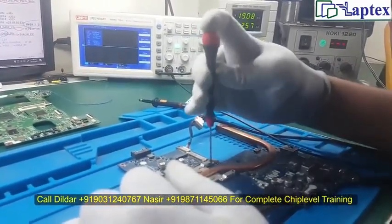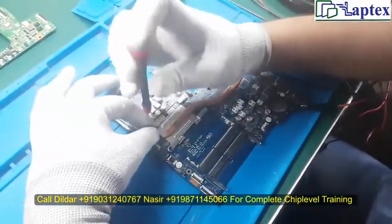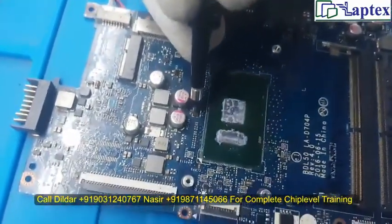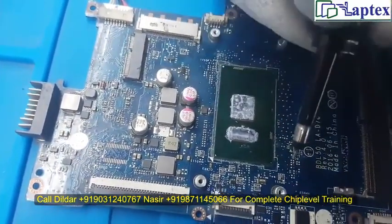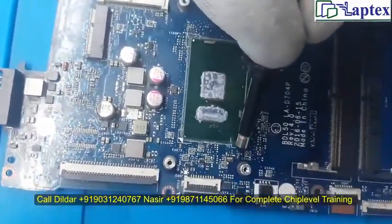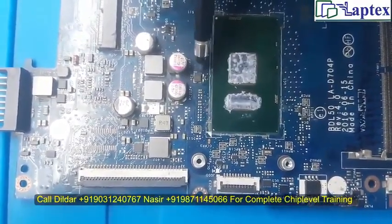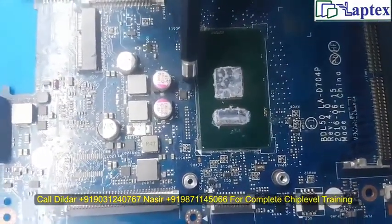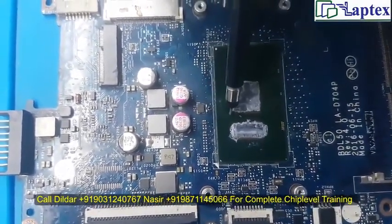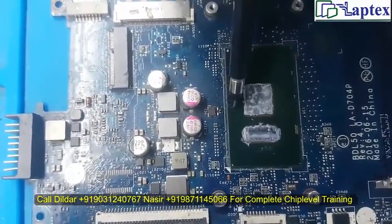Instead of checking on the crystal, I recommend checking it on the capacitor or on the resistor. Every time you will see, like this is also a crystal, this is also a crystal, there would always be two terminals. If it has 4 legs, only 2 legs would be working and 2 would be NC, not connected. Of the two working pins, one would be the input from the PCH, and the output will go into the PCH.